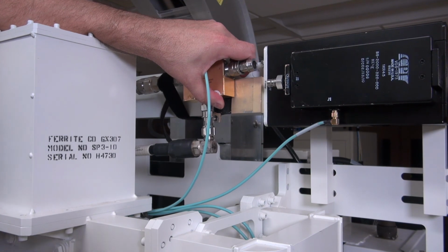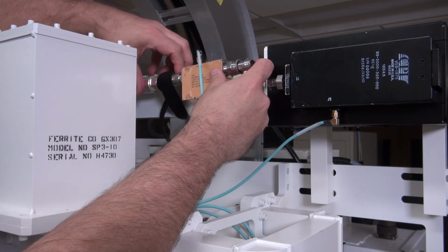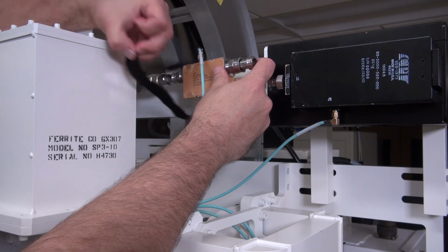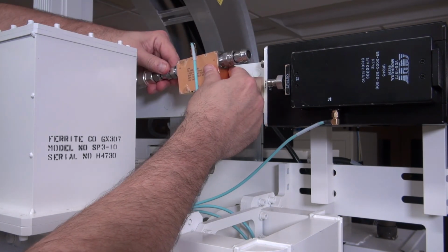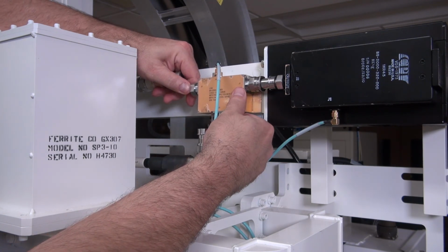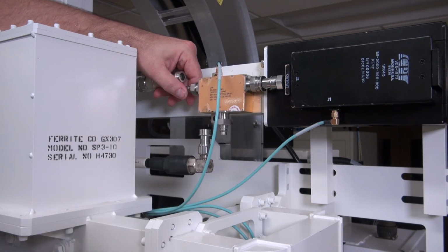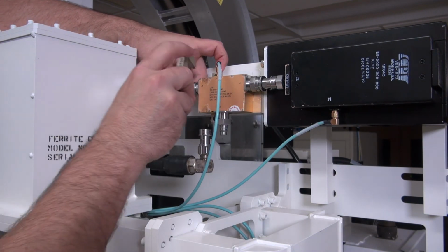The sequence of the following procedures reduces the risk of damaging the LNA. Disconnect cables 2W556 and 2W577 from the LNA. Connect LNA 2A5A4J1 to TR limiter 2A5A1J2. Ensure the quick disconnect adapters make a good connection.